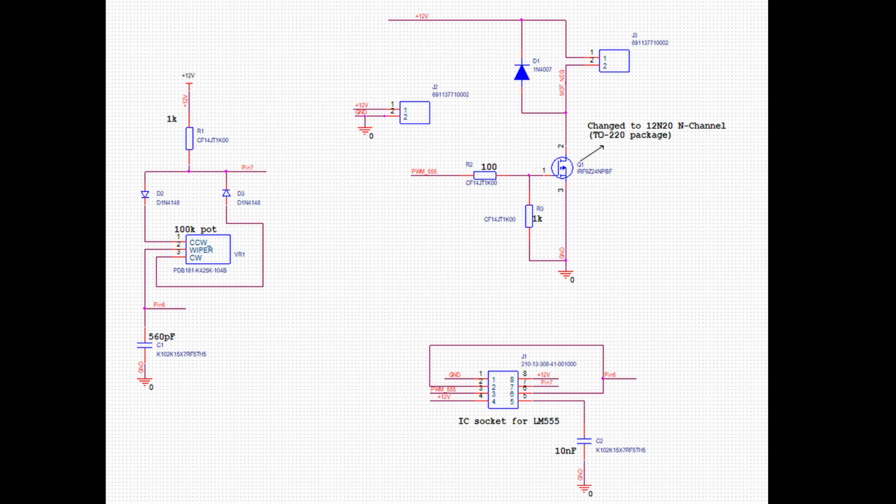The sum total of the charging and discharging times is the period of the signal. If the potentiometer charging resistance is high between pins CCW and wiper, the discharging resistance correspondingly goes down, since only the remaining of the total 100K resistance is seen between pins CW and wiper.